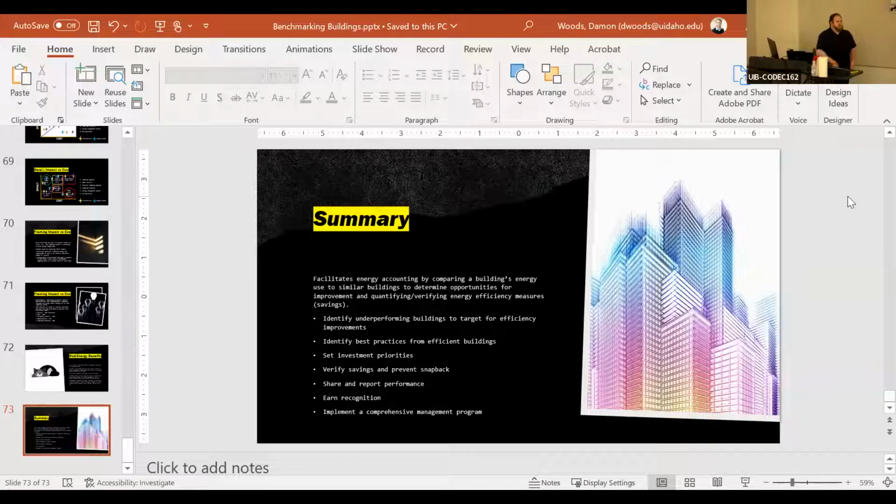So the most common multiplier is climate. Depending on the climate zone you are in, it will change. For comparing your building, a building operating in our climate versus one operating on the East Coast is going to be completely different. It could be a school, 5,000 square feet, same operating schedule, same equipment, but because of the climate, that's going to drastically change how you operate the building and where the set points need to be.